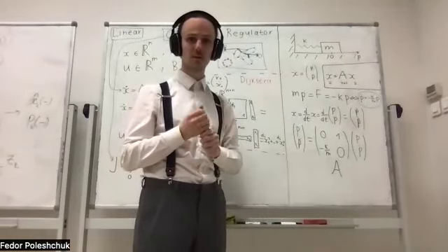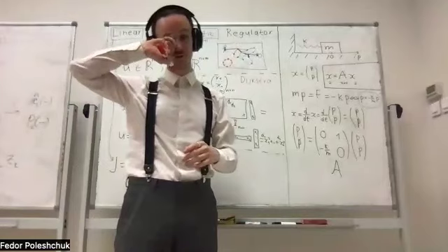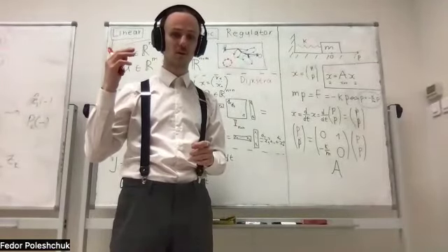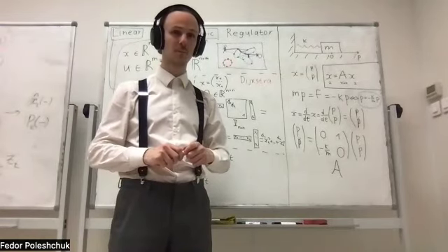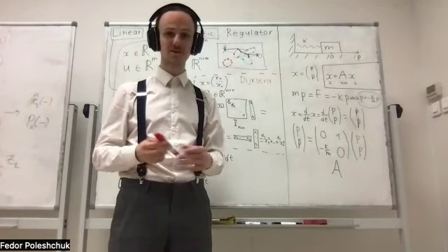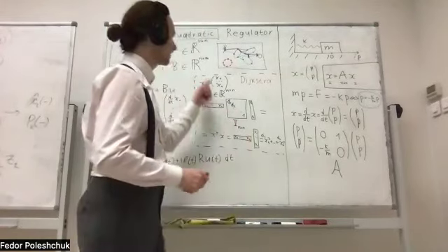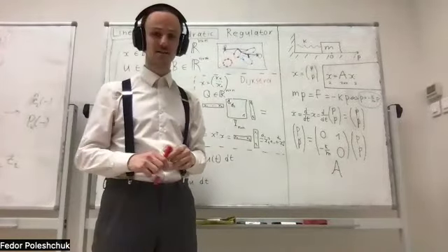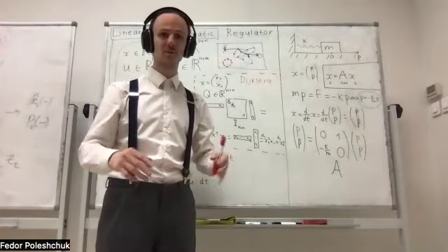Okay. So after we have planned the high level path for the robot, it has to follow this path. And in our robots, it is done with the so-called walk engine. The walk engine is the intermediate level of control that takes this desired trajectory as an input, and outputs the steps that the robot has to perform.